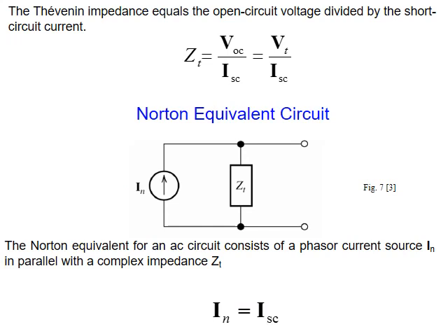What about Z Thevenin? Z Thevenin is V open circuit over I short circuit across the terminal. V open circuit is V Thevenin, we defined it, and this means I can also reduce the circuit between A and B to a current source in parallel with the same impedance. So Thevenin and Norton are the same.